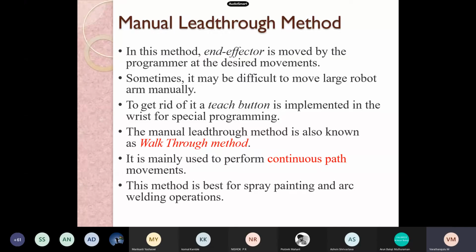The most common example of this kind of application is spray painting, in which the robot wrist with the spray painting gun attached as the end effector must execute a smooth, regular motion path in order to apply the paint evenly over the entire surface to be coated.